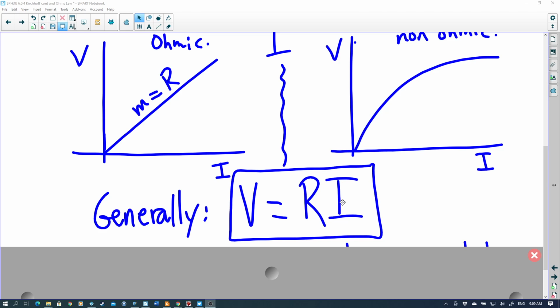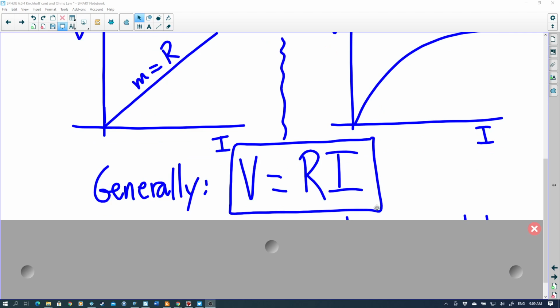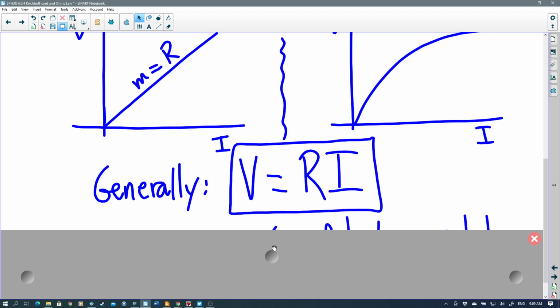If your current has to be 2, 2 times 10 is 20, your voltage would have to be 20 volts to allow current to pass through that resistor. Now it could be higher, okay, but the minimum would have to be that number. So if your resistance is set and your voltage increases, your current is also going to increase, which means voltage is proportional to current, okay? Or current is proportional to voltage, I should say. So that is the equation that relates those values together.